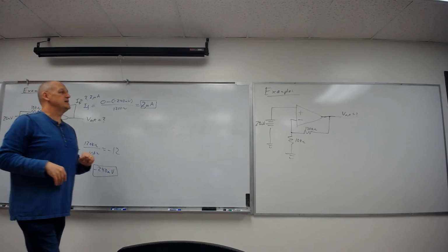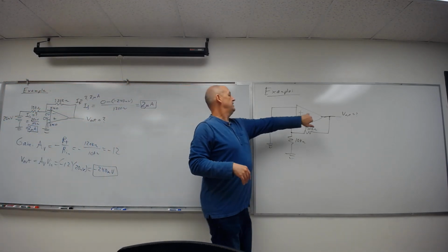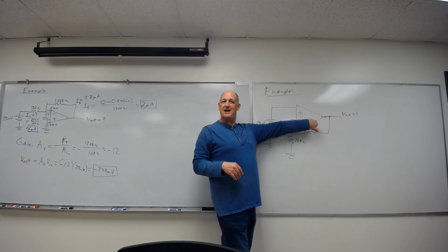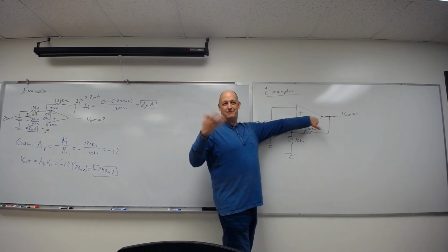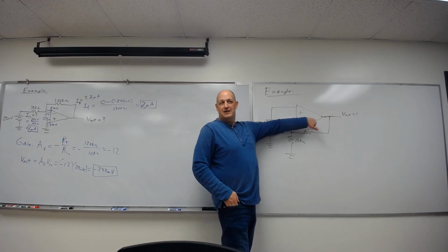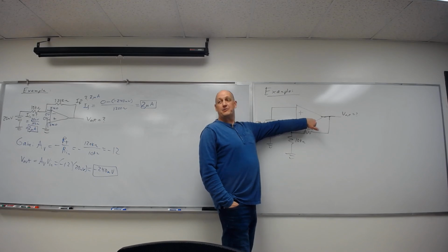The other it does is it allows for the individual variation of op amps, because these things are inexpensive. We buy them by the hundreds of thousands to put in things, and they have some variation in the internal gain, 10% or 20% or something. That way I don't have to worry about testing each one.